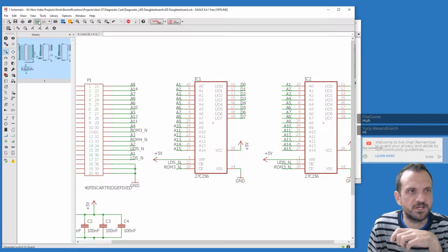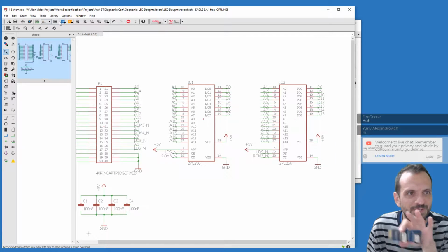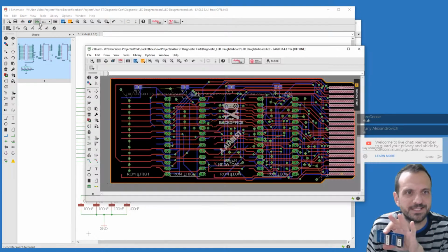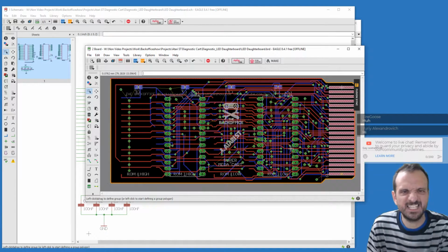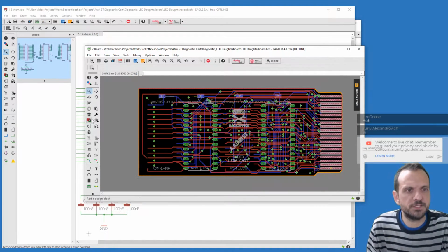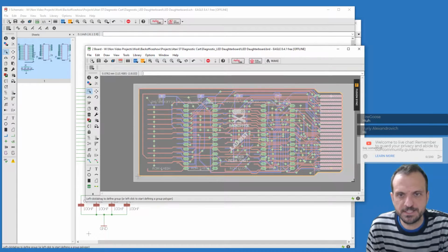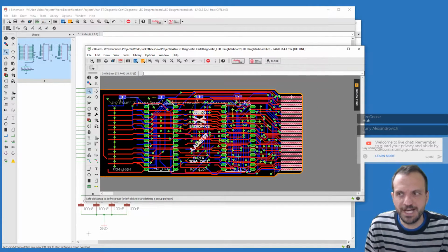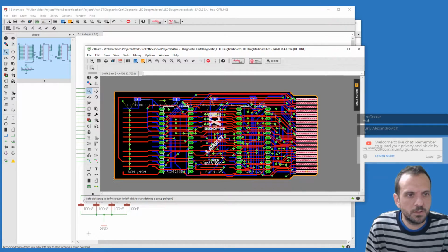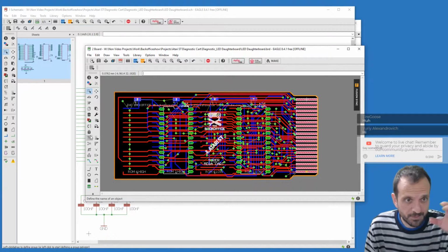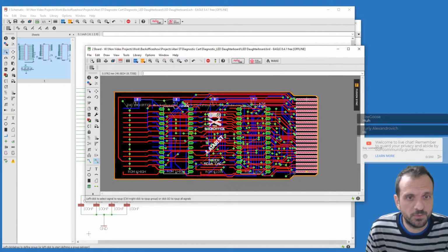And if I flip this over, interestingly enough, you'll see this is kind of cool. This is why basing it on your existing design is cool. So that's the outline. What we can do is, if we remove, I'm going to pull up the rat's nest, and if we actually remove the edge connector, we have a really good basis to make a board that will just slide on over the other one. So we can get rid of those.